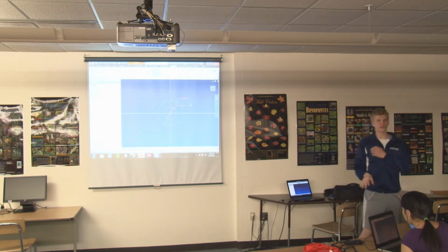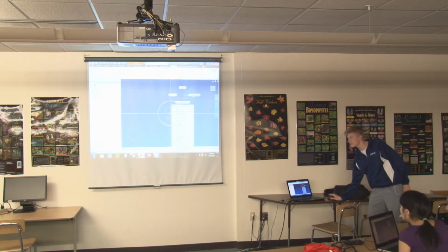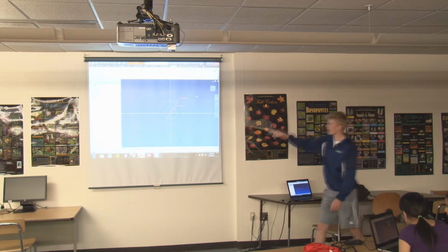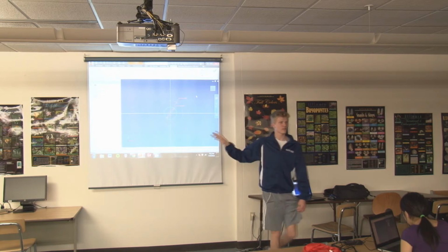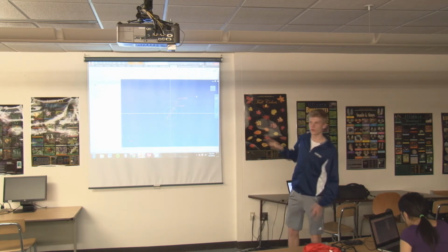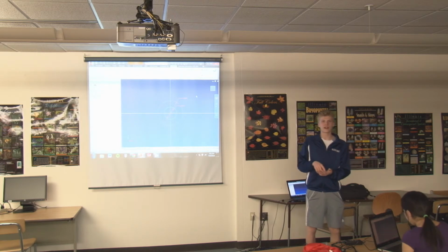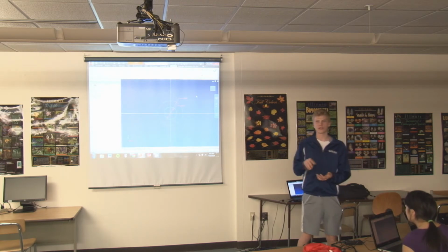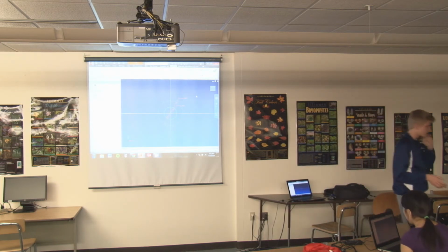So what you can do is right-click on this circle here, and that handy little button, Construction, will make it a dashed line. Now when you go to use your extrusion tool, it won't recognize that that circle exists. And when it comes to making closed shapes, it won't recognize that that circle is closing off the shape. So you can use that circle as a reference point for dimensioning the other objects without having to worry about what the circle does to your final extrusion.